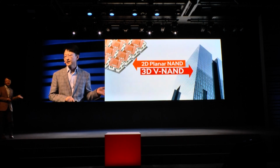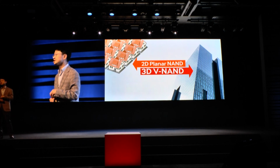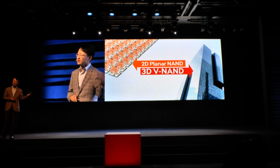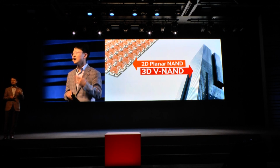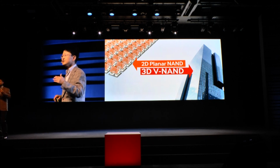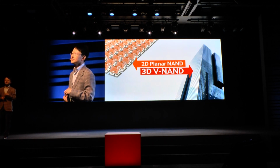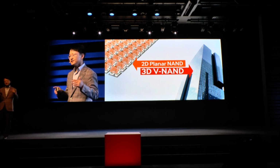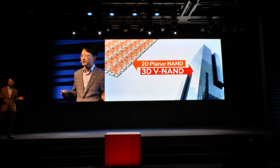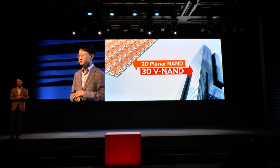The idea of 3D planar NAND versus 3D V-NAND is similar to living in houses versus apartment buildings. If you want to increase the number of houses on one row, you'd have to build the house smaller, right? It's just like increasing the number of cells in 3D planar NAND. On the other hand, in the case of apartment buildings, if we want more houses in the same area, we just need to add another floor without worrying about reducing the size of each apartment. This is what 3D V-NAND is all about.